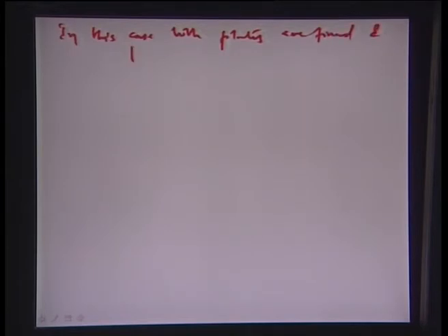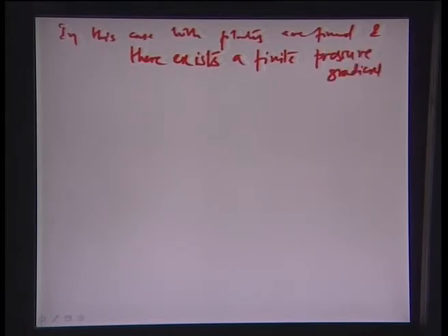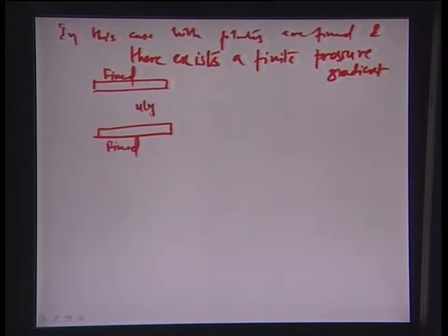And there exists a finite pressure gradient. Okay, that is why it is pressure driven. So, essentially you have two fixed plates, this is fixed and this is also fixed, with u as a function of y in between.